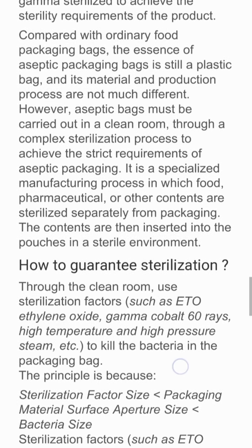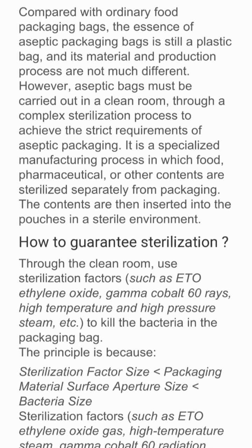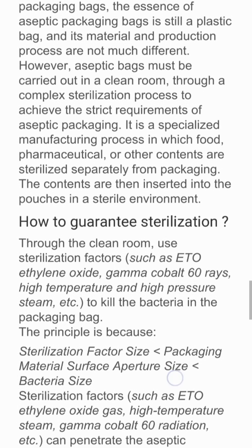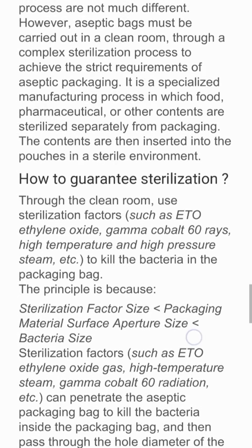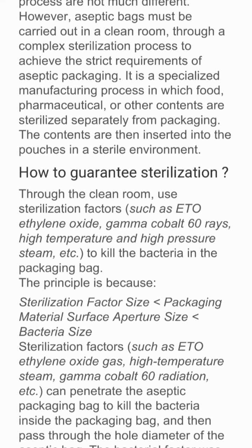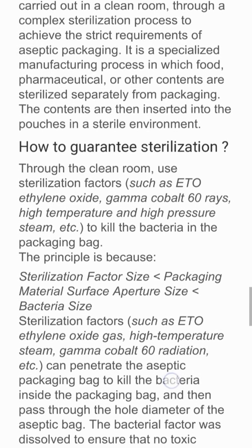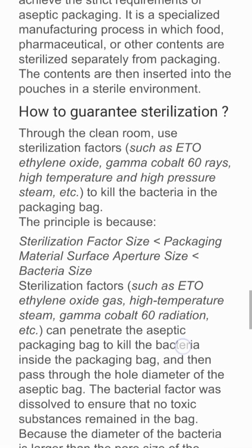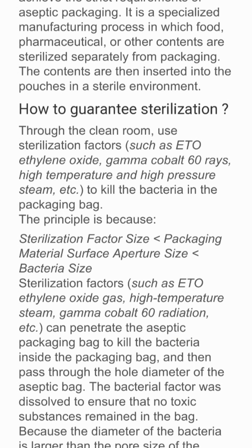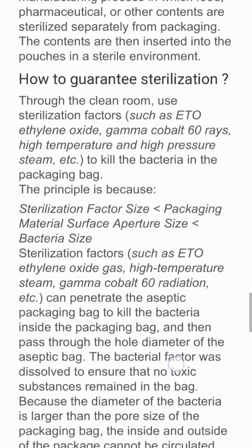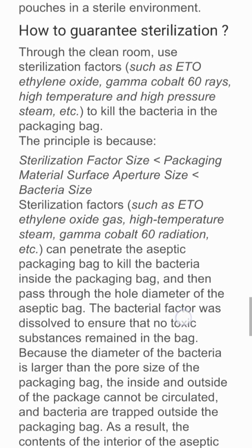Compared with ordinary food packaging bags, the essence of aseptic packaging bags is still a plastic bag, and its material and production process are not much different. However, aseptic bags must be made in a clean room through a complex sterilization process to achieve the strict requirements of aseptic packaging. It is a specialized manufacturing process in which food, pharmaceutical, or other contents are sterilized separately from packaging. The contents are then inserted into the pouches in a sterile environment.